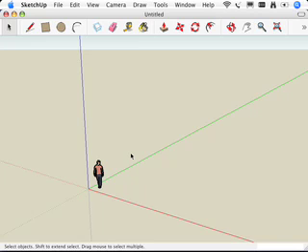This video is for Google SketchUp for Dummies. It's called Injecting Accuracy into Your Model. It's really about using the VCB, which is the Value Control Box. It's this little white area in the bottom right-hand corner of your screen. It's where you enter dimensions and lengths and distances and radii or radiuses or whatever they're called, so that you can work with actual dimensions in SketchUp.